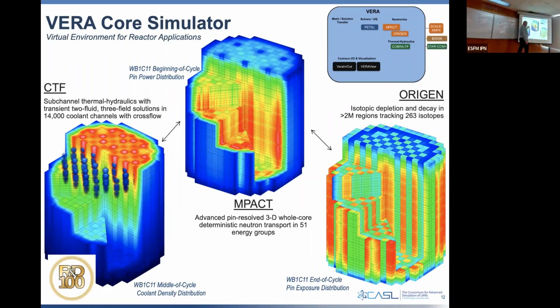The Impact capability can resolve 3D radiation transport. Some features you sometimes see pop up here are these little lines that are a little lighter. That's where the grid spacer is. And so you can actually see where the power dips inside the grid spacer. In here, these little bubbles that are coming up, we plotted where the subcooled nucleate boiling is happening. And so down here, there isn't any boiling, and it's not until you get up to about 2/3 of the way up in the reactor that you start to have the little subcooled boiling happening on the surface of the rods.